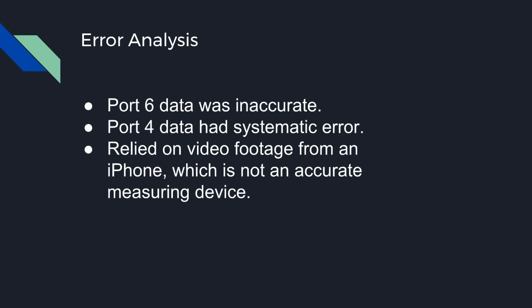When calculating the data for the Strouhal number, we were unable to clearly count the number of shed vortices, as the refresh rate on the iPhone was just not high enough when coupled with the poor lighting conditions in the wind tunnel. Thus, we were only able to count vortices at one of the slower velocities, hence that is why there is only a calculated Strouhal number for the test occurring at 550 RPM.